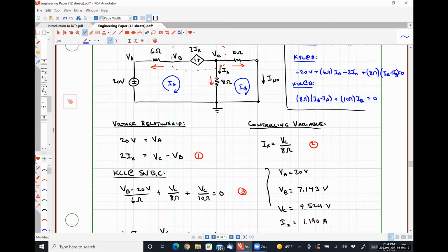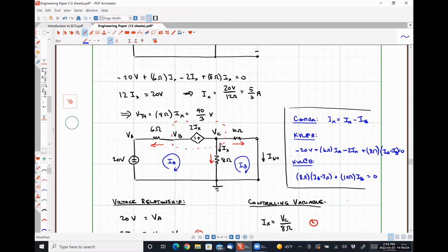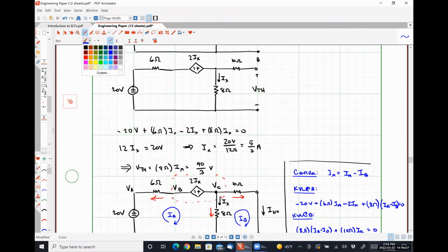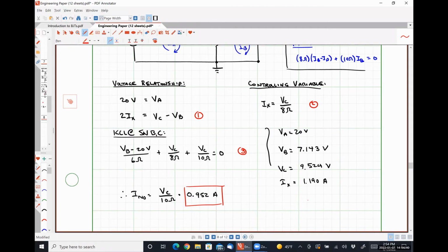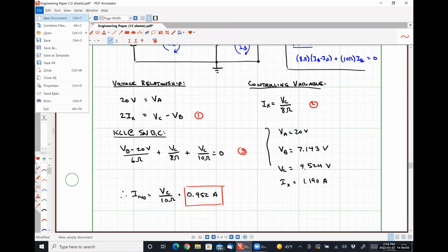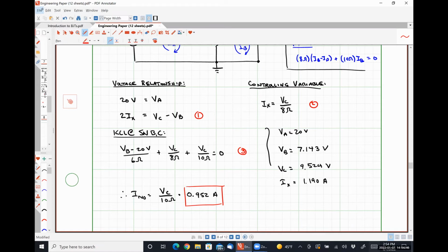All right, so we have found V Thevenin. I'm going to go up here. There, we found it. We have found I Norton. So my next question is, how do we find R Thevenin? V Thevenin over I Norton. That is a perfectly reasonable way to do it. Okay, I'm going to tuck that in right here.